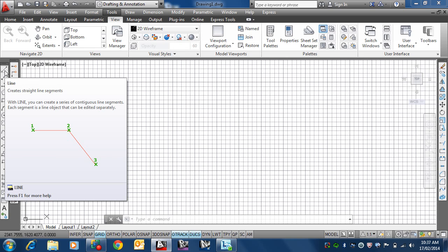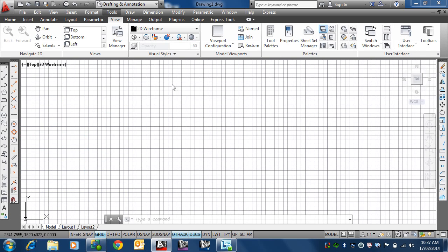Now, the enter in AutoCAD is basically the enter button, as well as the space bar, except for when you're typing notes, and the right mouse button. The mouse also does a couple of other things. If I draw a line in here for now, I'm just going to type in L enter just to show you this.